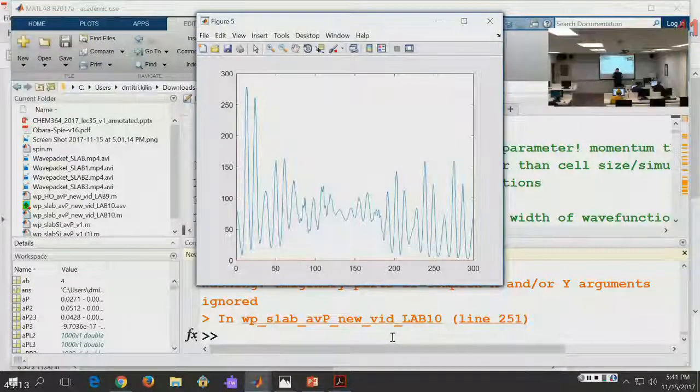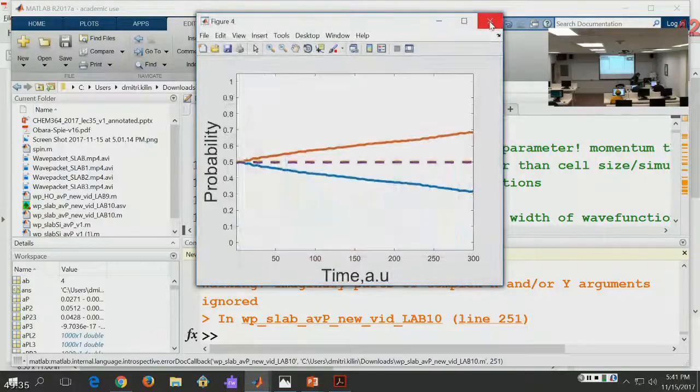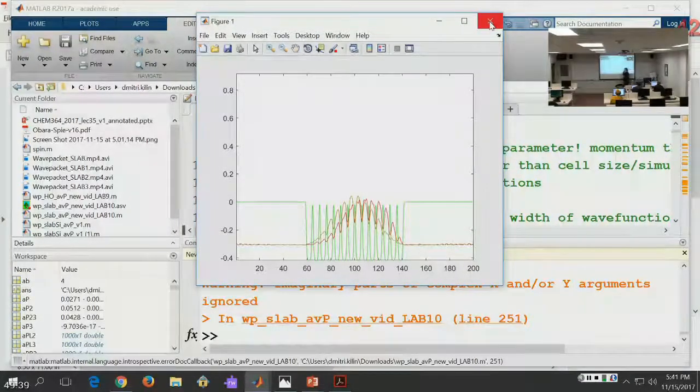And then it makes one layer hold too many electrons, a little too many, and another too few. Then upon photoexcitation, an electron can migrate between these two layers. So this is what is going on in silicon technology, and we can model it here by picking one of the atoms and making it lower, which means it will lack electrons, it will be an electronically accepting doping, or we can lift the height of one of the atoms and it will be an electronically donating layer.